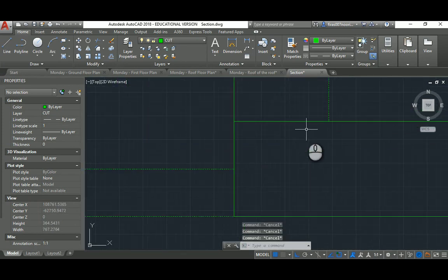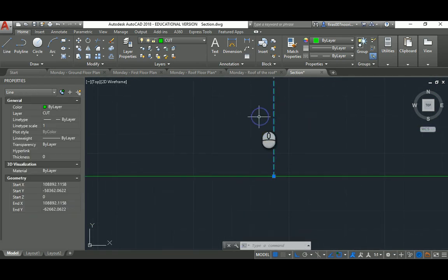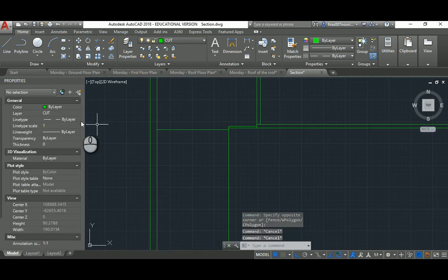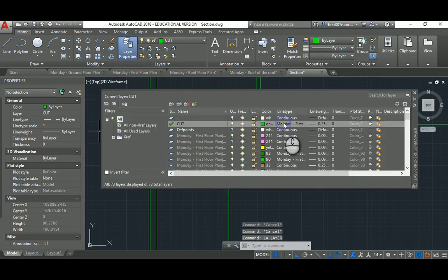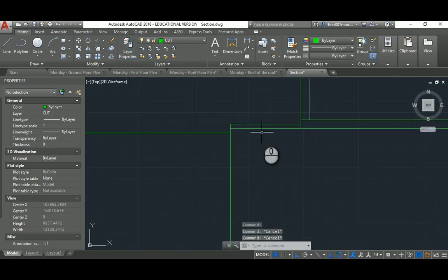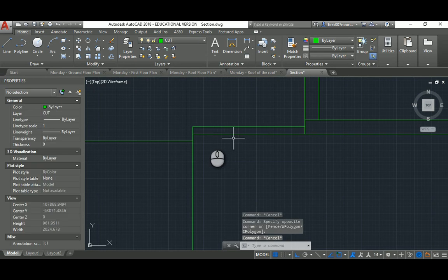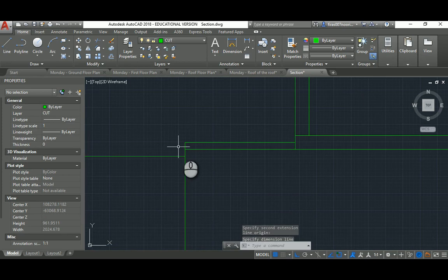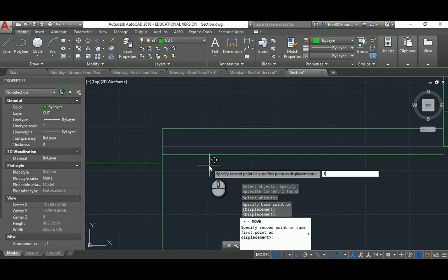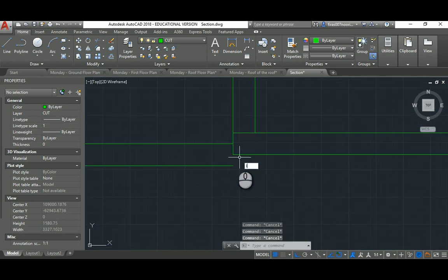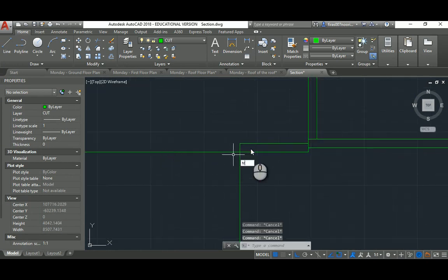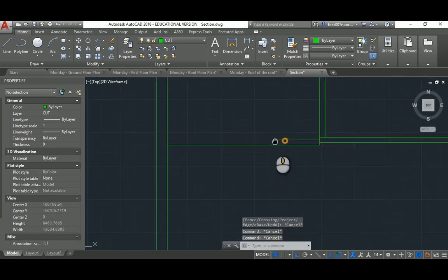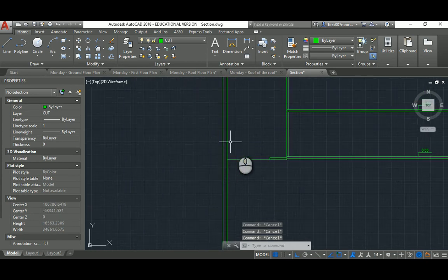No. And I noticed that some of my lines are just dotted. Oh god. Anyway, it's by layer. Okay, that's why. So the line type is incorrect, so it would be a good opportunity to fix this issue. Yeah, fixed. So again, this line should be 300 mil. Perfect. So I'm going to push that another 100 mil, and that's basically it. That's my walkway. I know it's too thick, but I'm just too lazy to do it the other way. So that's it.